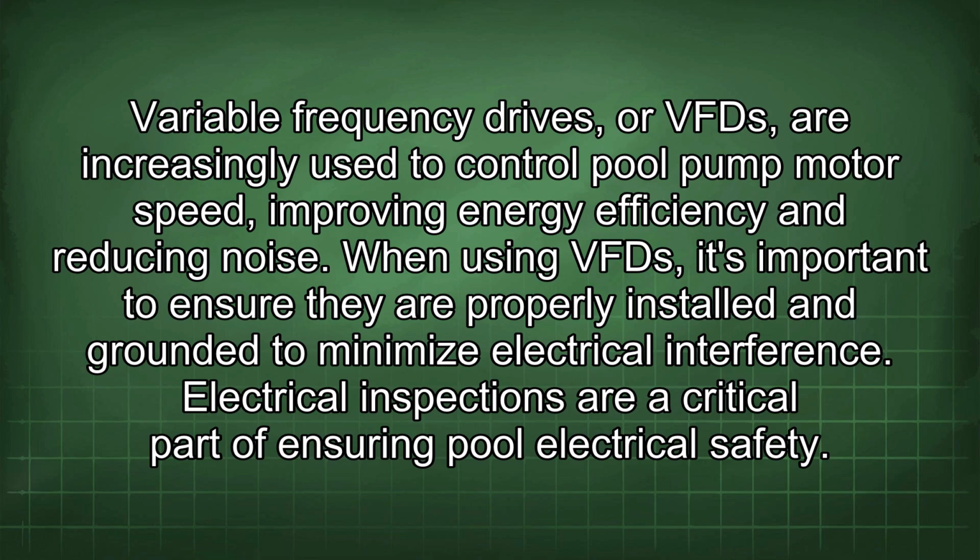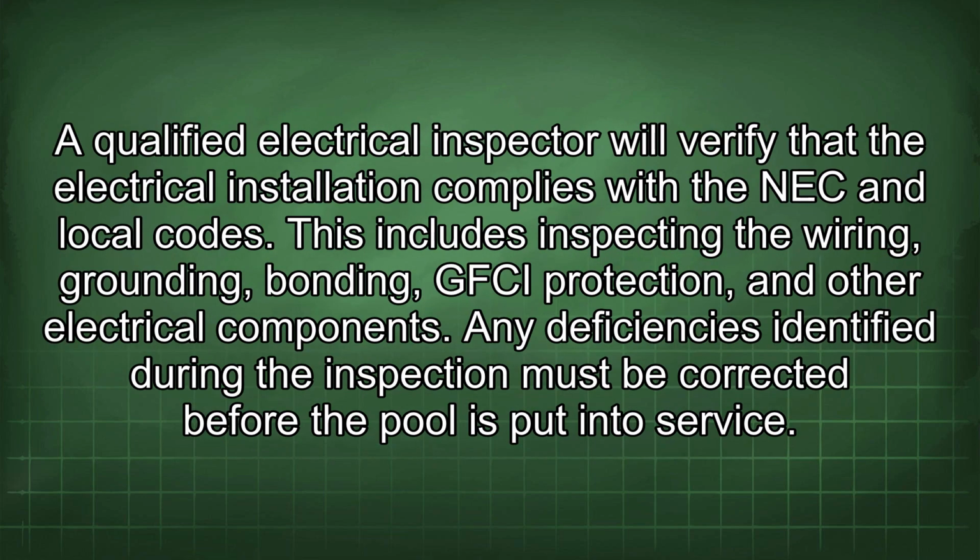Electrical inspections are a critical part of ensuring pool electrical safety. A qualified electrical inspector will verify that the electrical installation complies with the NEC and local codes. This includes inspecting the wiring, grounding, bonding, GFCI protection, and other electrical components. Any deficiencies identified during the inspection must be corrected before the pool is put into service.